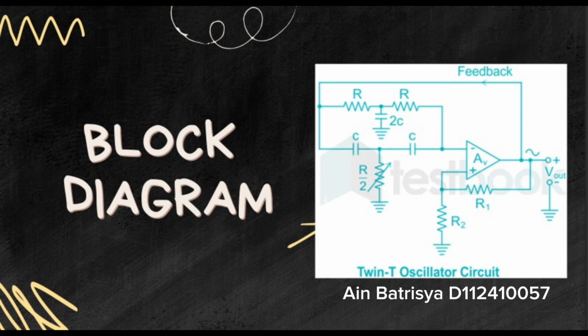The positive feedback is applied through the twin-T network, and negative feedback is set by the resistors R1 and R2, which control the gain of the amplifier. Finally, the output is taken from the amplifier and provides a clean sine wave labeled as Vout. This sine wave has a frequency determined by the values of the resistor and capacitors in the twin-T network.